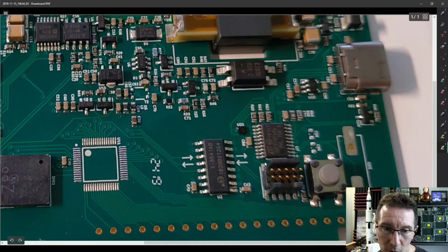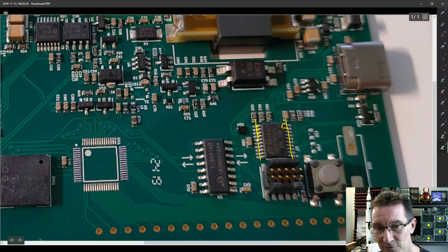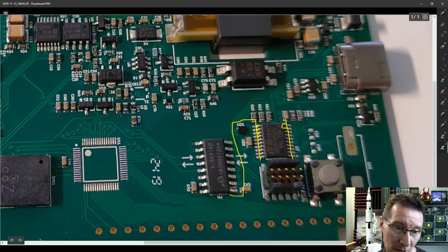So we could do that, or what we could actually do is have our Flex going like this through the pads like this, and then have little castellated pads on here, right? Little half moon castellated pads. And I've shown those, I'll do it exaggerated here, okay? So imagine that's one little pad, and then you slice through them just like you would on a regular FR4 fiberglass PCB. You can do that on Flex as well, and then you could just solder in like that. And then the board could actually be like this.